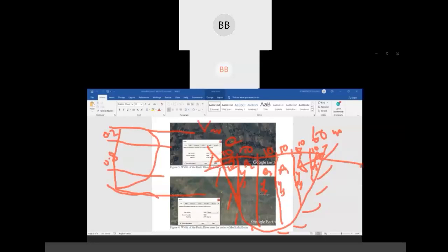So they are saying that to find out the average velocity, you have to find out the velocity at two sections, that is 0.2 and then 0.8, and you take the average of both. Then you will get the average velocity for a particular section. So what you have to do, you have to use this equation for each area. Suppose here, for this particular area, you have to find out the average velocity by using this concept.